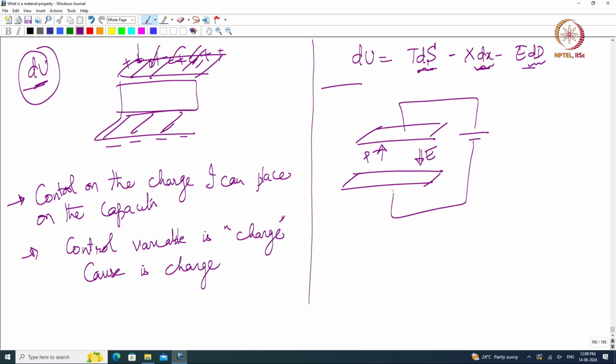And then the polarization suddenly flips, right. So, at a certain electric field the polarization flips. At E greater than E c the polarization flips. When the polarization flips, there is going to be a huge current or huge charge that is uncontrollable, right, through the external circuit, because the current so far is only a very minimal capacitive current, for E less than E c.